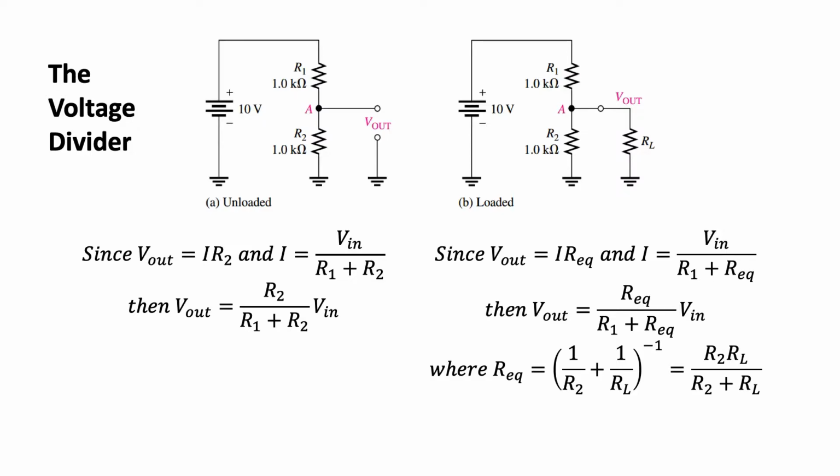It's composed of a voltage source in series with two resistors. Across one of the resistors, typically one that is connected to the ground, a lead wire is attached in order to tap the voltage. In the figure, Vout is the voltage across resistor R2.